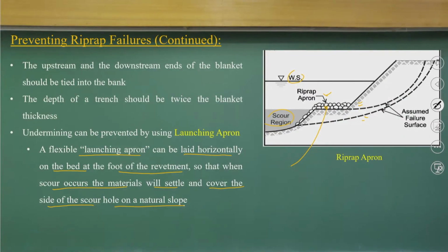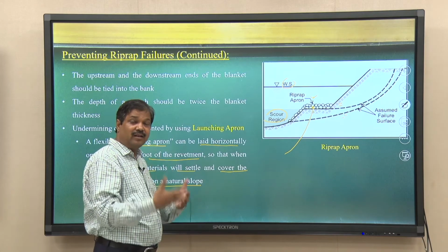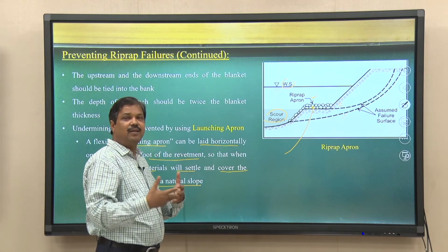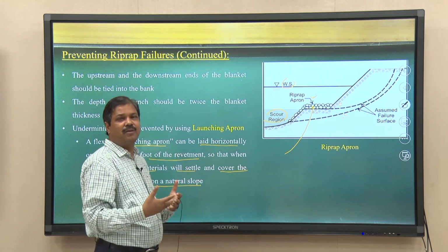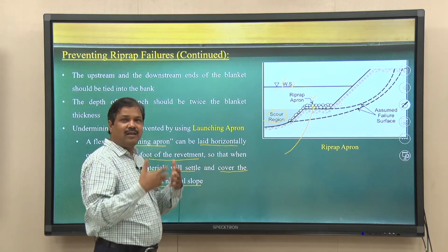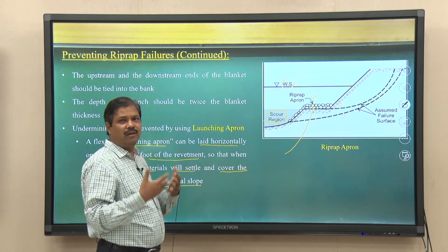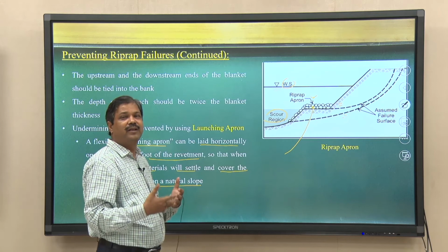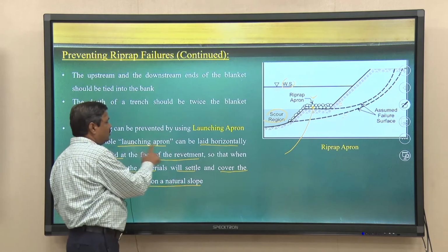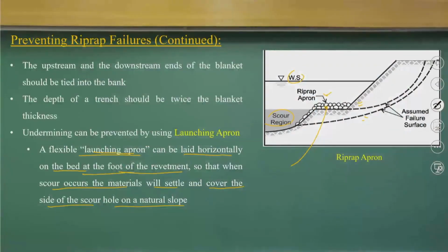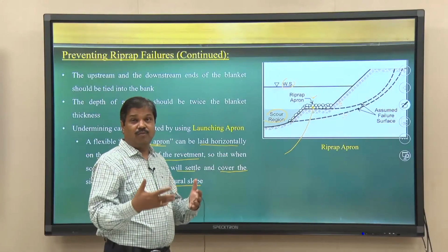That is the reason it needs a lot of experience at the river level. We design river revetment work, implement it, and monitor it to know what criteria should be followed for the launching apron, so that the river bank can be protected during the extreme scour formation stage.